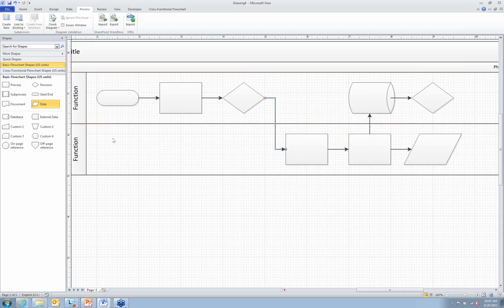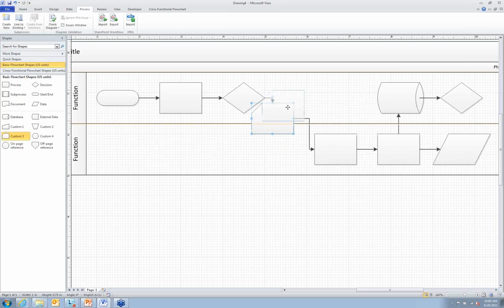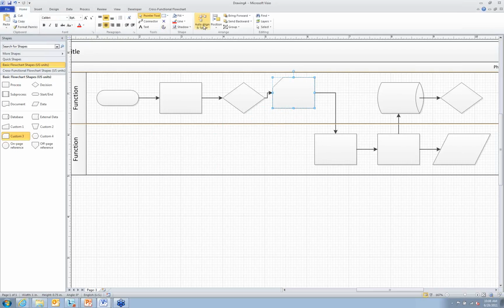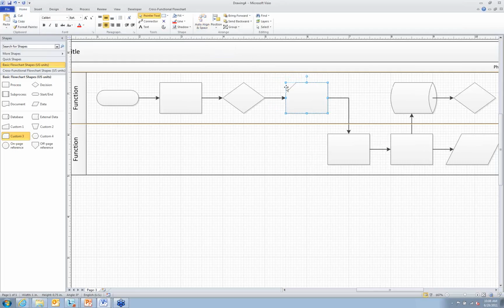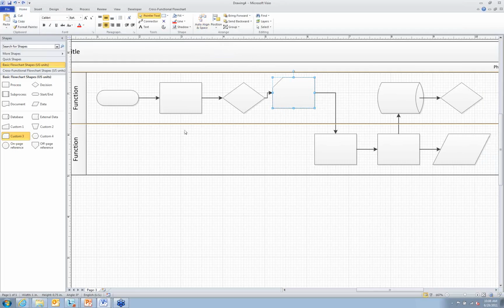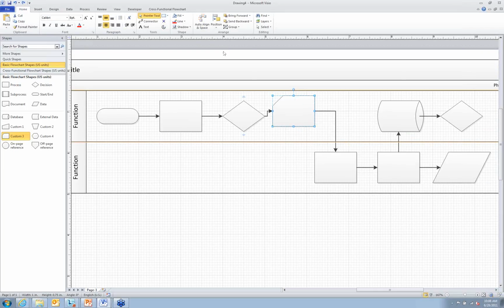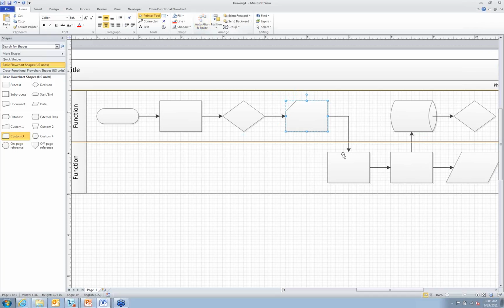Similarly, if I have a custom function I'm going to drop on the page right there and put between these shapes, it'll automatically add it in there. Now, if I put it in a strange place like this, where it doesn't look that great, I can use the Home tab and click Auto Align and Space. Let me do that again. The diagram goes from something a little less visually appealing, with this jagged edge right here, and with one button, Auto Align and Space, the diagram looks better. So that's part of just adding and deleting content and making sure it all fits quickly and nicely.